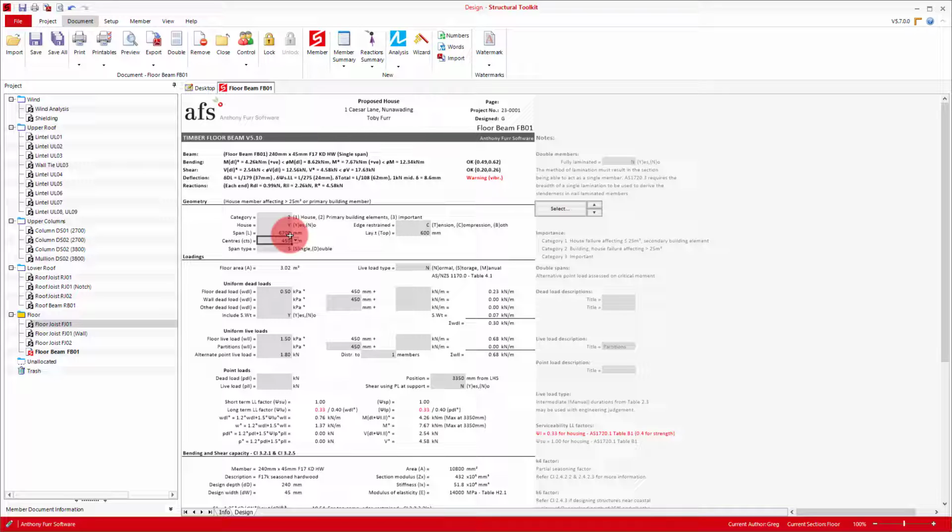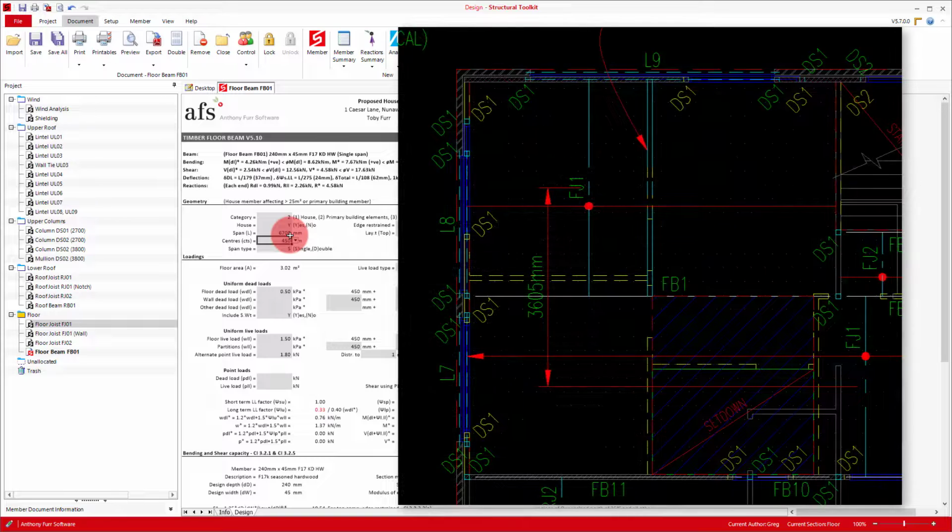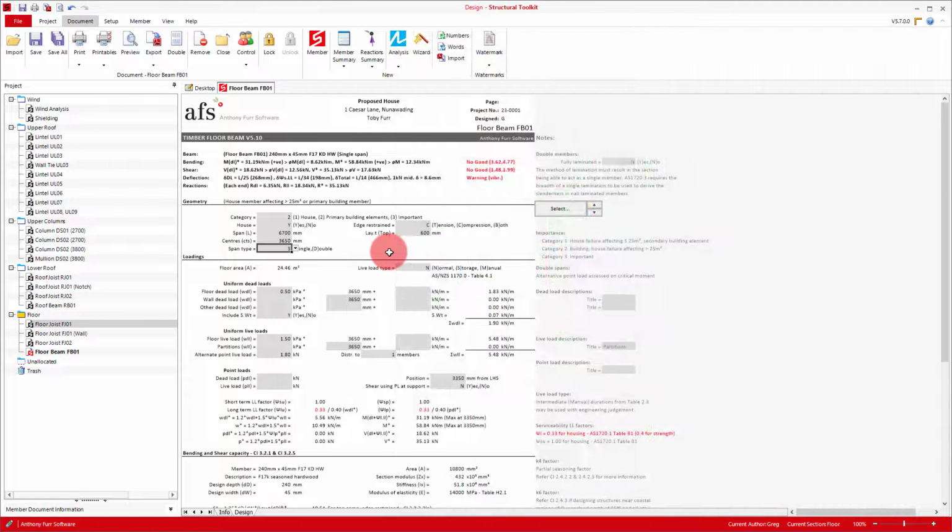To a bit better demonstrate the design process, we'll pretend we don't know yet that it won't work in timber. With our span already in, next is our centers, which will be half the joist span either side. This measures at 3,650 rounded up. Our restraints along the beam will be at 450 centers, being the spacing of the joists.